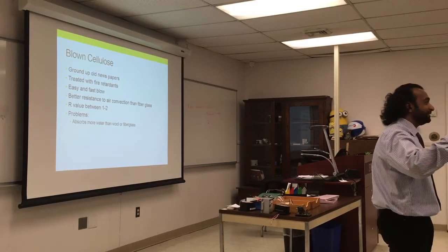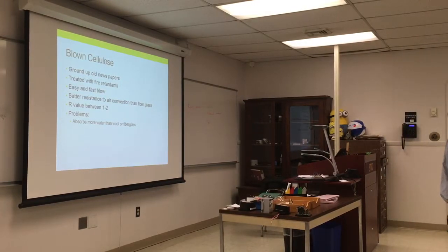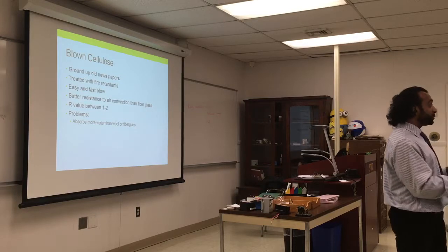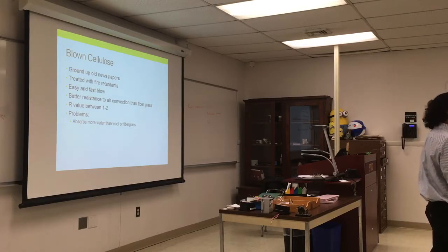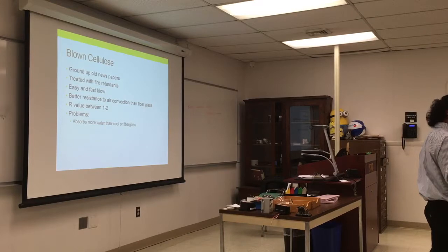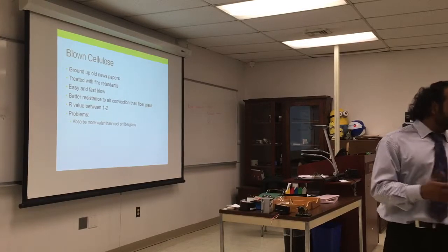The point that's very interesting is venting to the attic. I've seen that in a few houses where the bathrooms vent to the attic and it has a window. That's really not a good idea. You get ice dams, and what else do you get? Moisture. With moisture comes bacteria and usually mildew. So that is a really dumb idea to have in a house. You can get a hose or duct and take it to the outside. Just opening a window is not enough. If you see that, that's a big no-no.